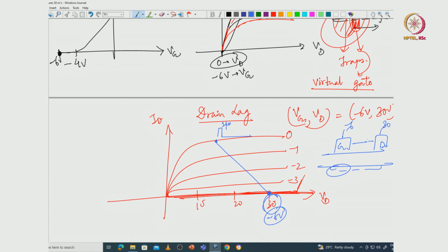between the gate and the drain, so some part of this is also depleted, because it is blocking this 30 volt. So it is a high stress condition. You are not only depleting this, the field lines also go deep into the buffer. You are reaching deeper layers in the buffer, and also depleting the 2DEG laterally between the gate and the drain. So two things are happening: one is the surface is coming into play more prominently now, I will come to that, and secondly your field lines are also penetrating deeper.